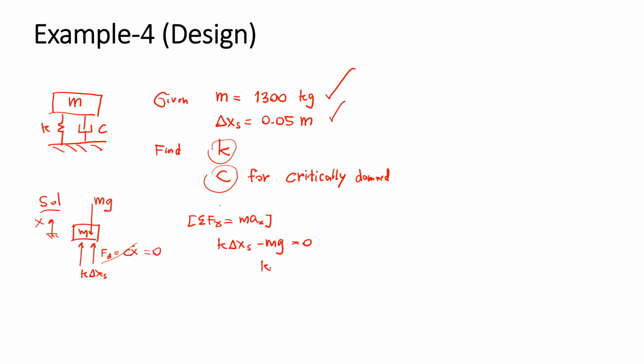So K equal to mg divided by the static deflection. So you will obtain K, the stiffness of the spring.